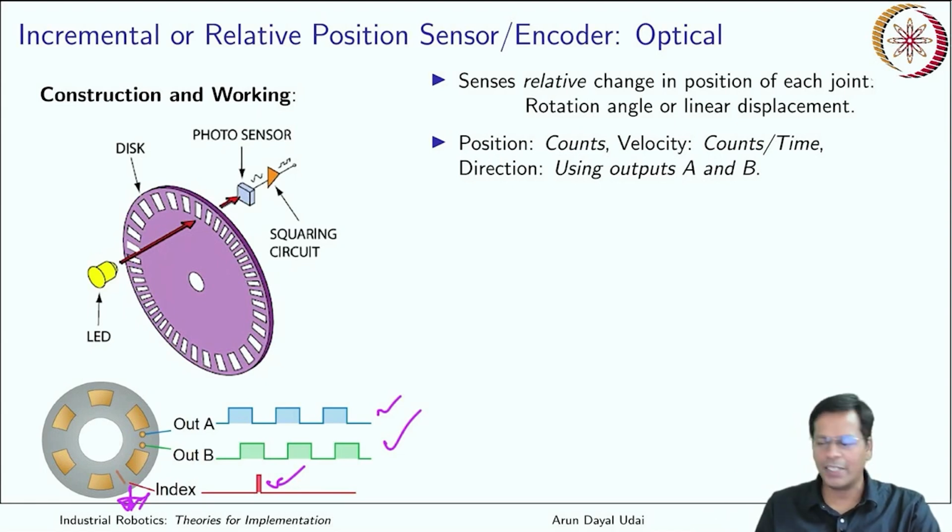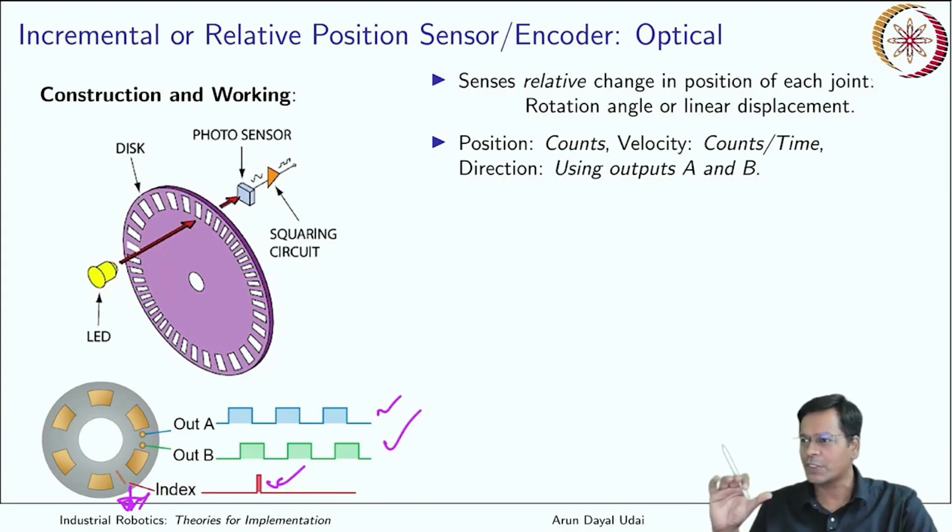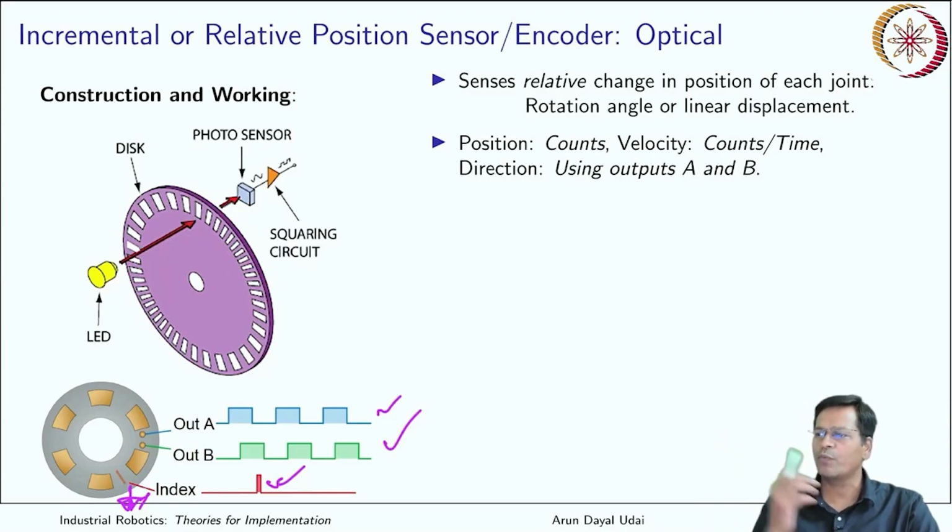Okay, you can directly get that. This will also save you from counting, let's say, 360 high signals for one complete revolution. So for every 5 revolutions, 360 times 5 counts are going to appear. To avoid that huge number in your variables, you can just keep track of your index.